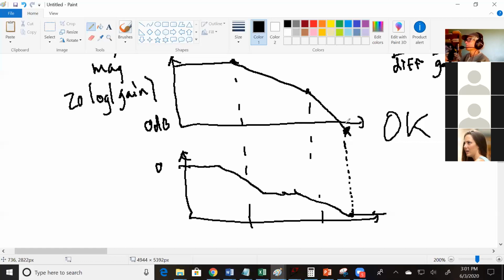I know that went really fast, but just one more question. Again, we'll go over this next time. How can a 0 mess this up? A 0 would prevent the attenuation that's caused by a pole, so that it may end up being above the 0 dB line. Yeah, a 0 will make this flatten out. It also brings the phase up, but depending on, that was a left-hand plane pole, right? No, it's a right-hand plane pole. Anyways, I'll fix that next time.